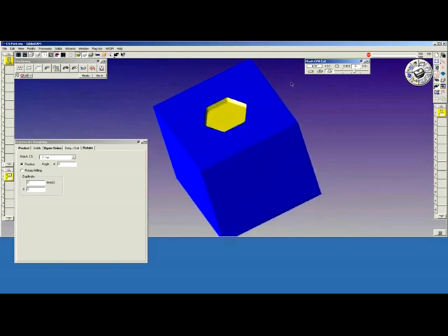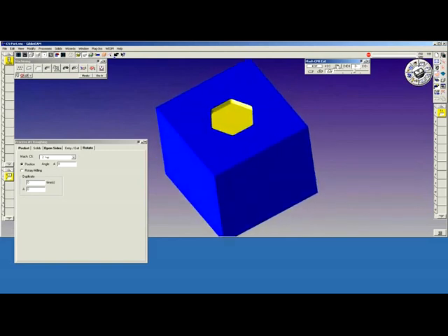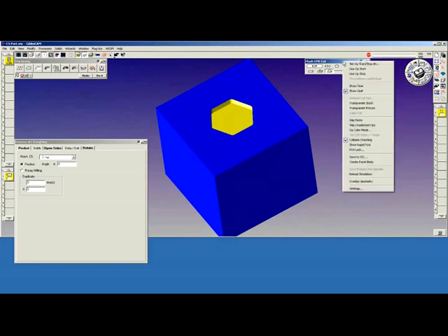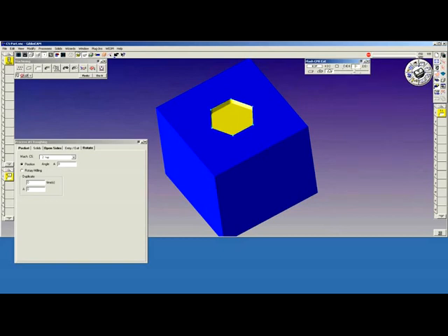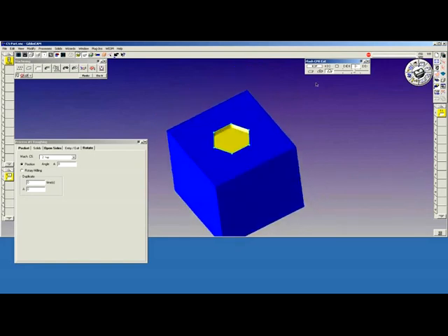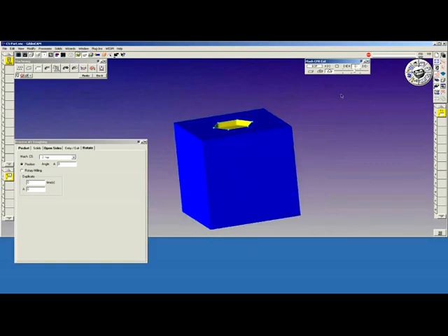In version 9, in the Flash CPR, if you want to see the geometry, you can right mouse click the top of the control panel and say Overlay Geometry. This will put the geometry superimposed on your rendered image, and you can actually leave it there, and watch your cutter and the geometry at the same time.